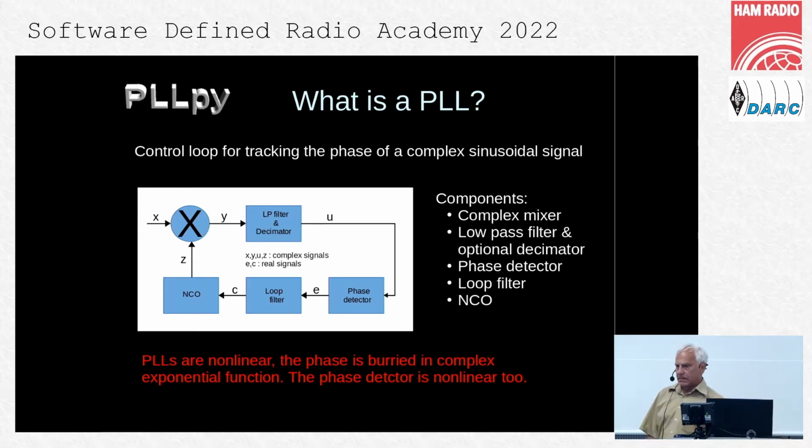This is why the PLLs are nonlinear devices. And if you would like to analyze the PLLs, you have to have linear models. You linearize this nonlinear model.